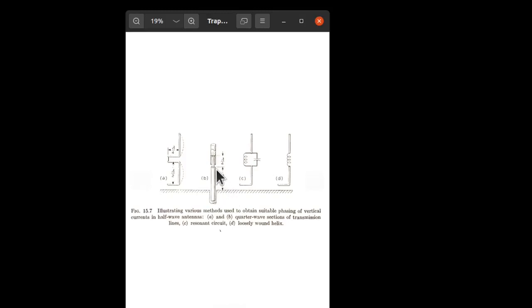Here we do it with a monopole and with a choke element developed by the internal structure of an open transmission line, which is each of these is equivalent to this lumped circuit of a tank circuit, capacitor and inductor.